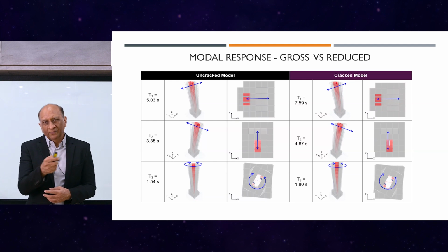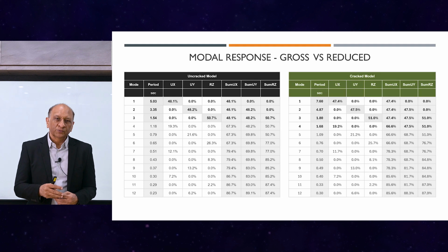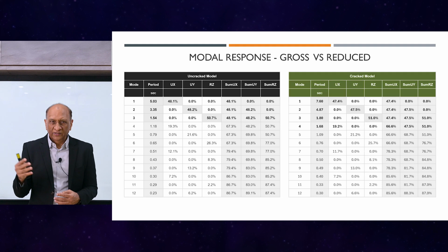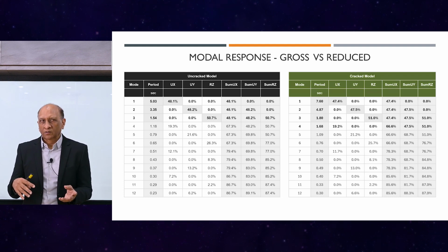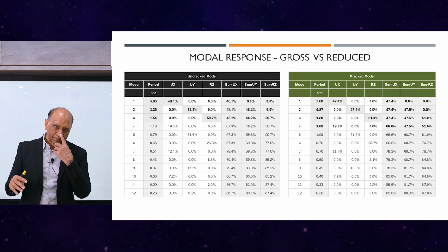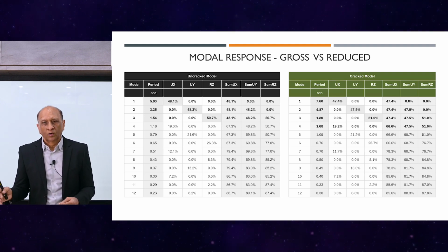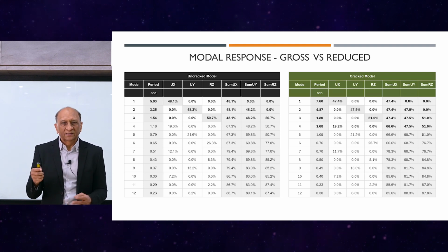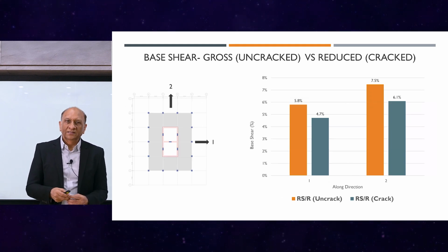So now you can see here that for a building of this kind, which is tall and the period is already pretty long, at the bottom of the flat portion of the response spectrum, the change in the period does not change the force significantly. And then we can see 18% in this case. And this is typical of a tall building of this kind, that even the cracked and uncracked section, or even if you include the soil structure interaction or don't, they do not affect significantly because the building period is already too long and is not affected much by stiffness change. And the same thing will happen with story shear and moment comparison. They also reduce in a similar manner, the same amount. And then we can continue to see the drift and the displacement in the same way.